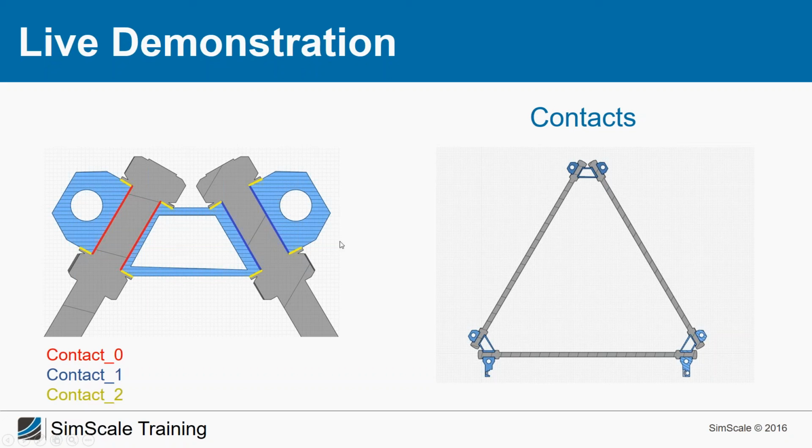And this, guys, is a very, very important point, maybe the most important point. Defining the contacts sometimes needs a lot of experience, because it's not a black or white solution. It's more like an approach you have to find. For example, here you could also ask, is it really correct to fuse the nuts and the rods into one part? I think no. It's not 100% correct, and it will definitely have an impact on our results. But from my experience, I know that the impact will be very, very small.